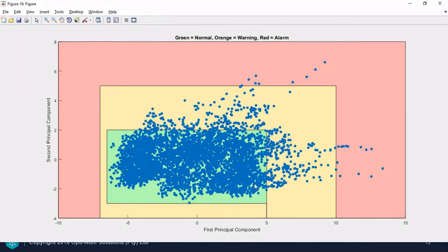If we look at the path of engine number 39, as we saw in the previous plot, we would see that it starts somewhere here in normal conditions, and as it is run for more flights, it progresses into the warning category, and it would end up somewhere over here in the alarm category. Now, this was where the engine was identified as faulty, so all of this does correspond. And note that these boundaries for our categories are only initial estimates based on our interpretations of the data.